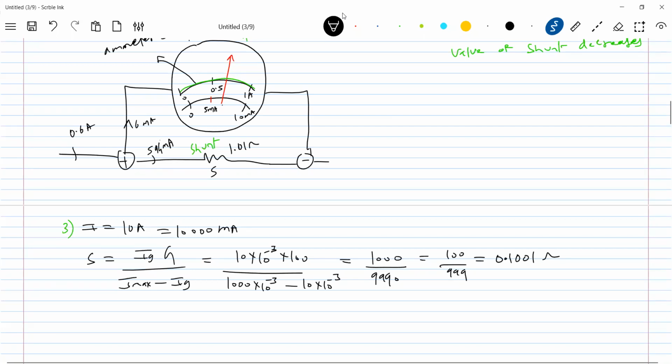So as I increase the range of the ammeter, the value of the shunt required will become very low. Manufacturing a shunt of such a low resistance, and that too with precision, exactly 0.1, then it will get converted to that particular range. Otherwise there'll be some error. So these are some problems I encounter for the low values of the shunt. I'll overcome this by some other method.